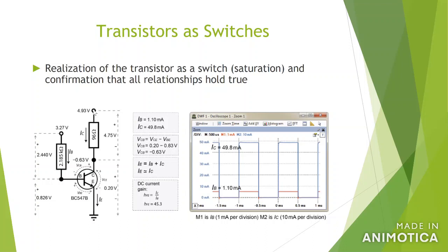Through the resistor, we connect to 5 volts. So for B and C, they use different power supplies. Why is that? Because for B, the power supply is from the Raspberry Pi, and for C, the power supply is used to drive a high current device.